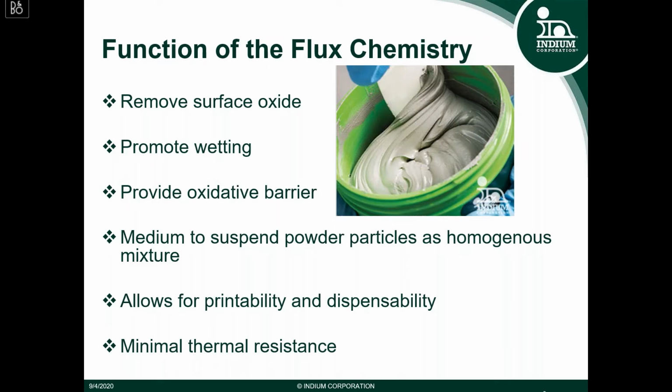So let's just talk about the flux chemistry. Essentially, the flux has a main purpose of removing surface oxides from not only your surface metallization, your PCB metallization or whatever you're soldering to, but also from the individual solder particles within the solder paste.